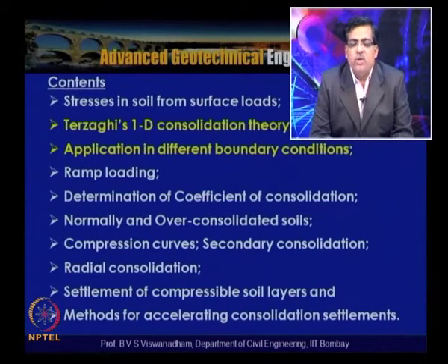Subsequently we will discuss ramp loading and how we can determine the consolidation characteristics of a soil, that is the coefficient of consolidation. There are two methods, and we will see how we can distinguish between normally consolidated and over consolidated soils. Then we look into several aspects like compression curves and secondary consolidation in the subsequent lectures. In this lecture we are going to discuss Terzaghi's one dimensional consolidation theory.